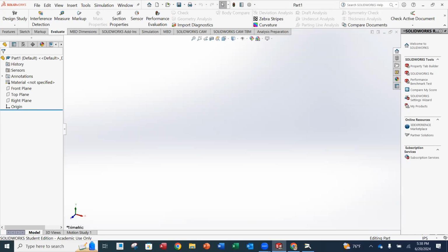So pulling up SolidWorks and just clicking on kind of the generic part template, when you go in there, you can just hit part just like we normally go in. And as we know, we would normally have to go up to our gear over here for the options, and we have to go into document properties and kind of change all that stuff. So we're going to do that one more time, but this time we're going to create a template, and we're going to save it so that you can then pull that template up, and you don't have to do all these manual changes anymore each time you make a drawing or each time you make a model.